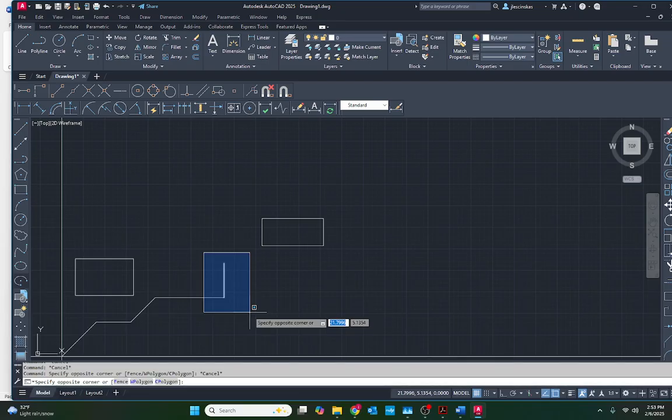When we go to the left, as long as we make contact, you can see how these highlight. That first horizontal section is highlighted, and as soon as I get to here, the next horizontal section is highlighted. So as long as we select a portion of something, when we go to the left, everything gets selected. So that's how we use select. Now, once you select, I'm just going to draw a separate line here that we'll use. We'll select this line. If I click on the middle of the line, that starts a move operation.